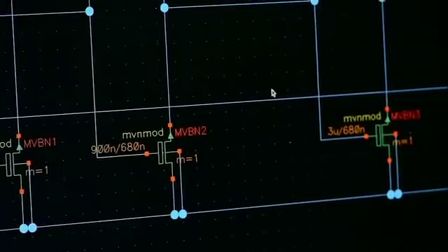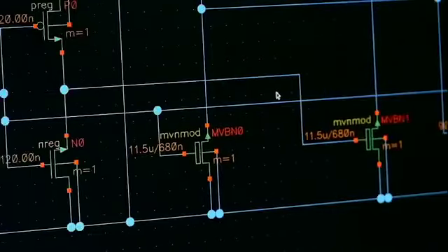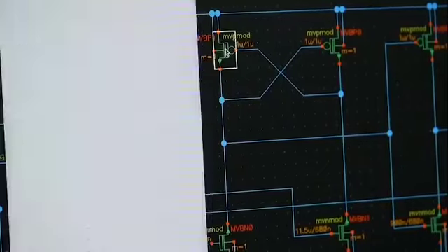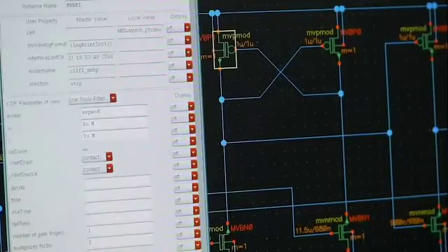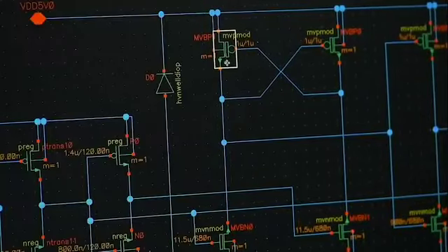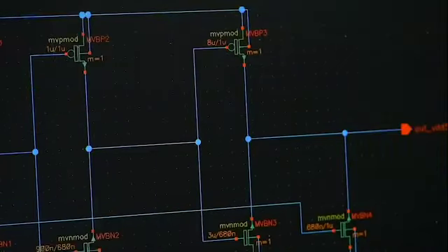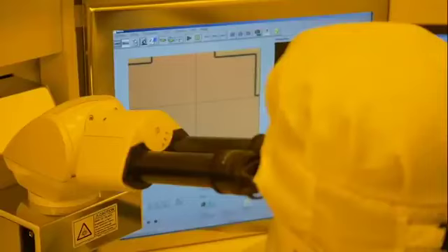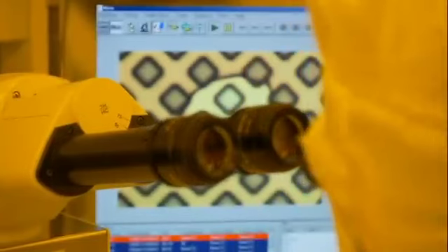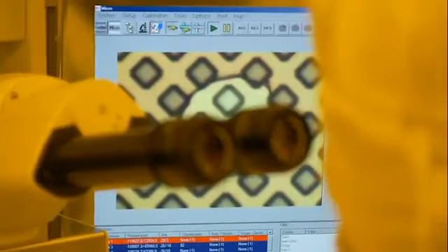This entails defining the chip's functions, simulating its technical and physical properties, testing its functionality, and working out the individual transistor connections. Special design tools are used to draw up the plans for integrated circuits and develop a three-dimensional architecture of sandwiched layers. This blueprint is transferred to photomasks. Providing geometric images of the circuits, the photomasks are used as image templates during the subsequent chip fabrication process.